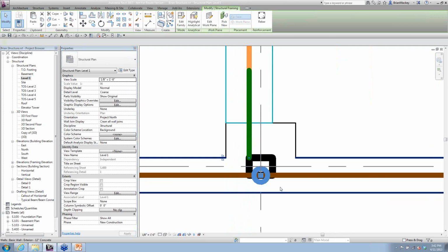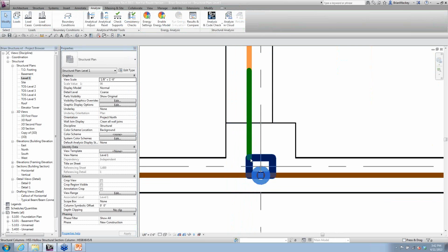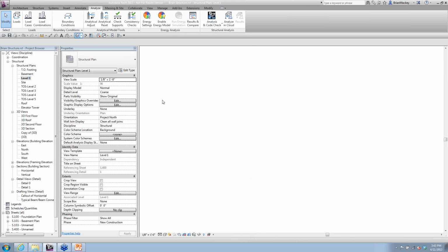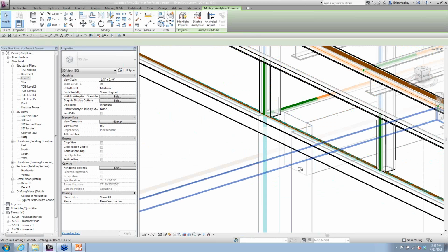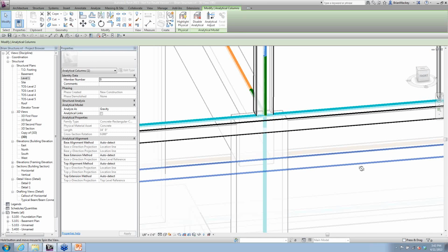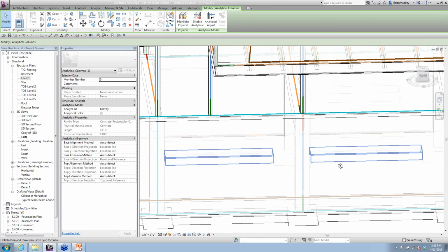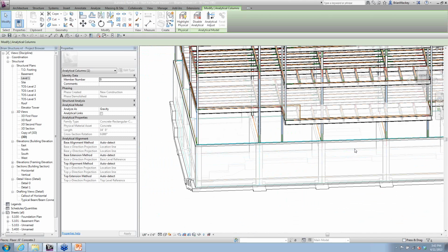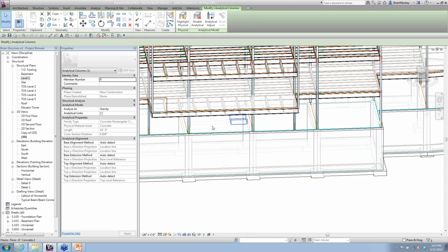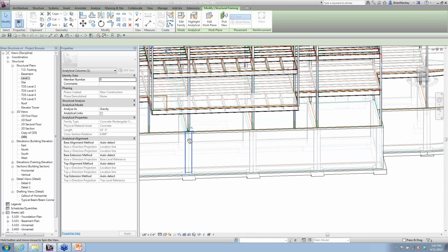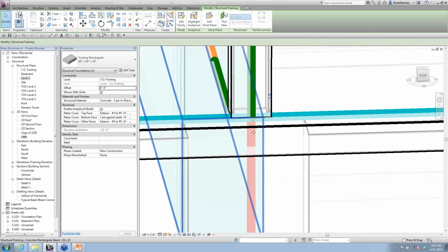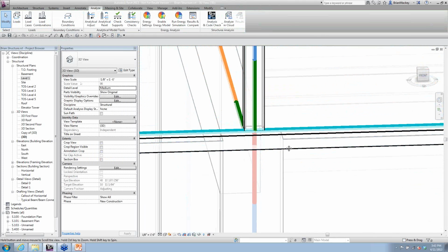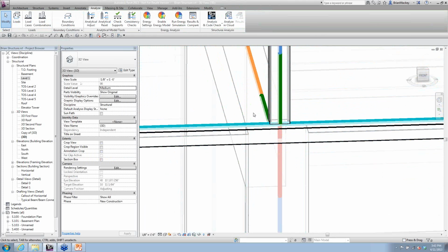So now that I have that moving over to there, there is no relationship for what it's doing inside of this area here. So it needs to understand that for that beam, I now need to have a rigid link. Or in this case, not the one, where is it? Which one did I just move? Not that one, because that's only an individual one. There it is. So you can see in this case, I moved it over now, and I've lost that connection from this beam to this column to the support. So if I were to take that out to an analytical program, the analytical program would more than likely see that there's a break here.